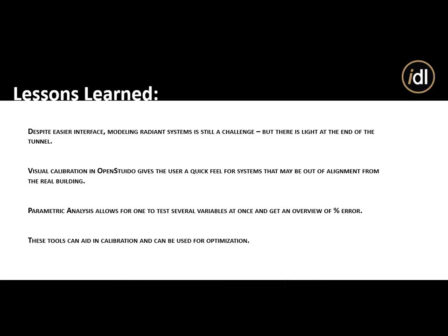So is it easy to switch back from EnergyPlus to OpenStudio, especially when it comes to set point managers? Because I run into that problem where you can only find them in EnergyPlus, and you want to switch them, you want to come back to OpenStudio, and how are you able to work around that?